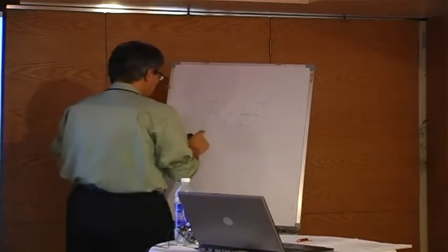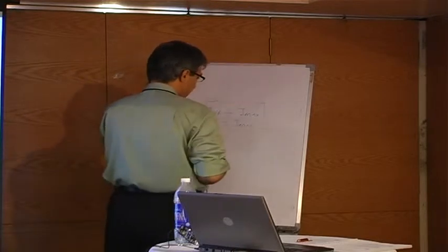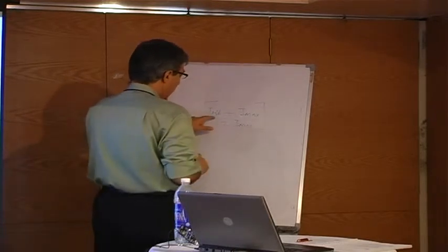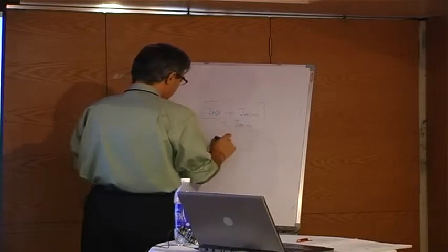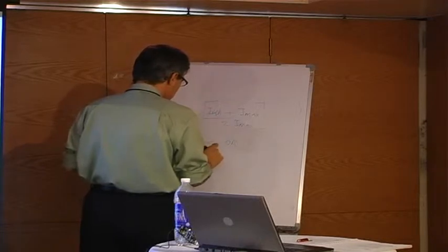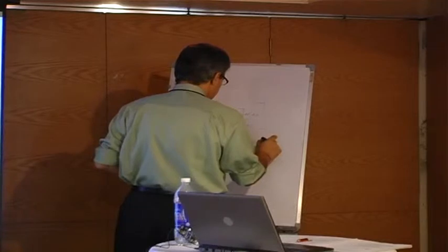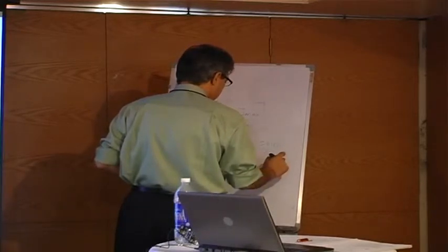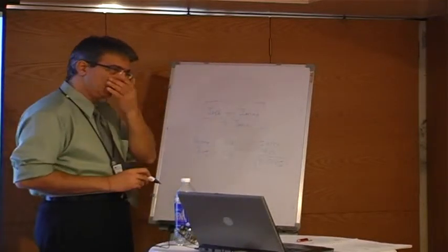So, and this is your I reference. You can call it I reference A. And Imax, for example, in this case is 10 amps. And I reference A we said was 5 amps. So basically 5 plus 10 divided by 20 gives you about 0.75. So that's a duty cycle command which goes into.